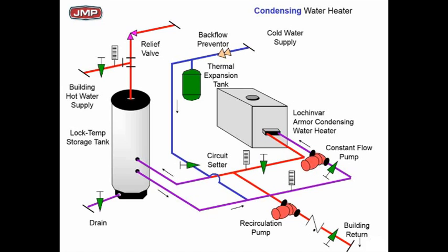Let's look at little red recirc pumps. You see that building return recirc pump? We want to focus in on that particular application, purpose of which obviously is to keep the water warm out close to the showers, close to the fixtures, so when you go to use them, you don't waste a lot of water.